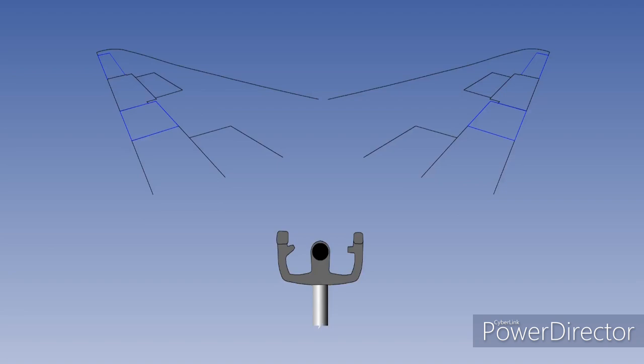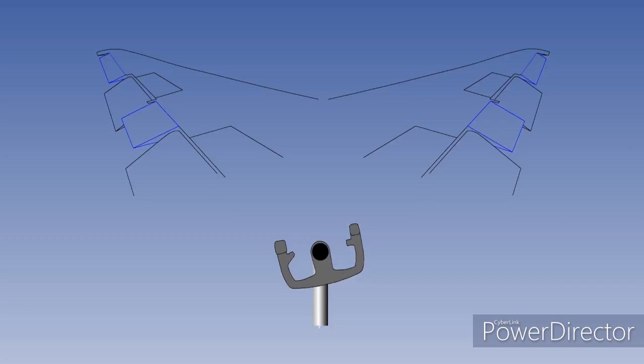When the trailing edge flaps move down, the flaperons also go down. Now the whole wing area has its camber increased, thus maximizing the effect of the flaps to increase CL max. But what about lateral control? Think of the flaperon position with the flaps down as a new neutral datum. When a roll input is made, the flaperons move up and down from this new neutral datum and still provide a change in lift on both halves of the wing for roll control.